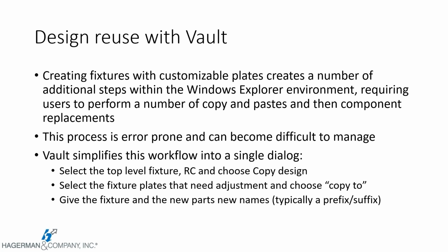So if I were to perform these operations, like creating a copy of a fixture assembly and then open that up and start making changes to it, I really run a high risk of editing the original files and not editing the new documents. And in all reality, I would have to do a bunch of component replacements inside of that fixture assembly in order to make sure that I've got the correct files loaded and linked. And beyond that, making sure that things like part numbers or any other pieces of metadata get updated, I'm manually doing that. So you're potentially running into a lot of issues or errors with that workflow.